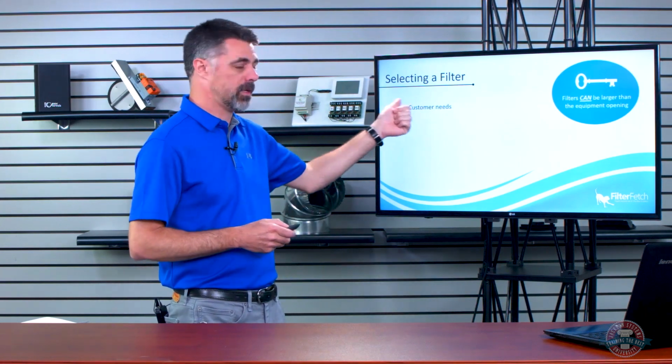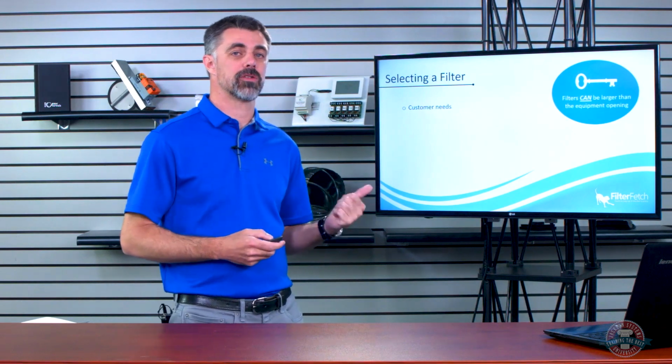Right, now, the first thing we need to look at when we're selecting a filter is our customer's needs. What does our customer actually need? Do they just need the equipment to be kept clean? Because if we get dirt on the blower wheels, on our secondary heat exchangers in a gas furnace, or on our cooling coils in cooling mode when it's wet, it turns into mud, we lower our airflow, we lower our heat transfer, and the equipment can't run right. The equipment's not going to operate the way it's designed to, and it's probably going to have a shorter life, so the customer isn't going to get what they paid for out of it. So we need to make sure we have a good enough filter in there to keep the equipment clean.